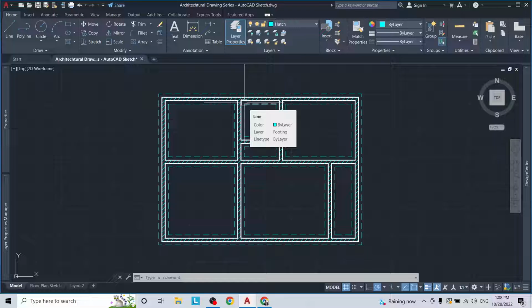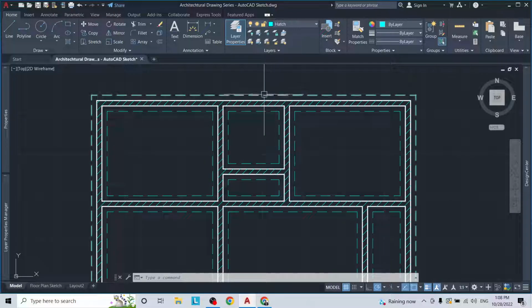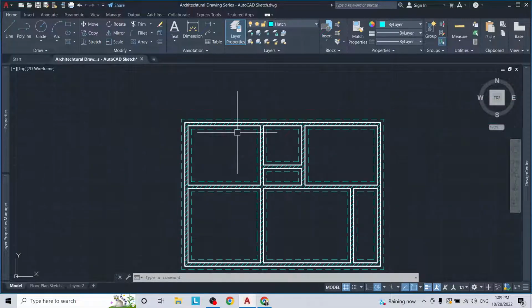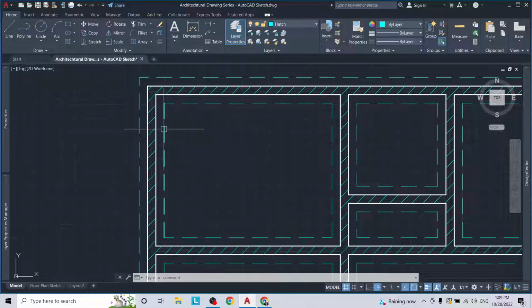You could use multiple methods, a combination of methods, or you could choose the one I'm going to show you now, but it must show the builder how wide this footing is, how wide these foundation walls are, maybe the space, the distance in between these footings.